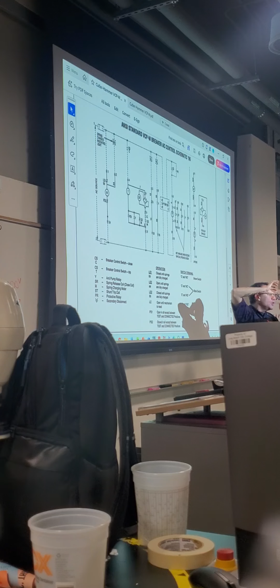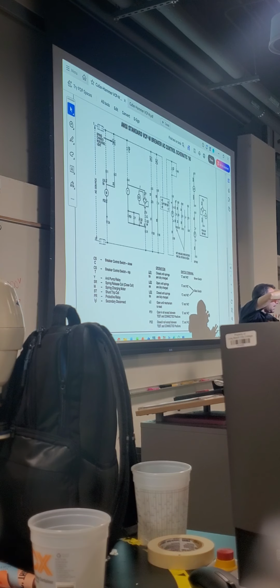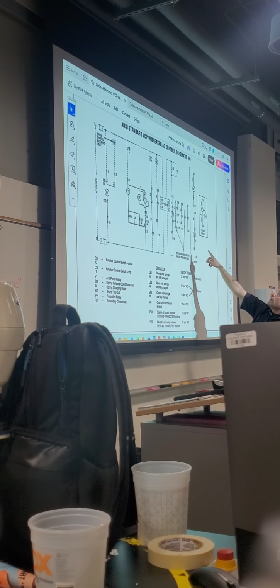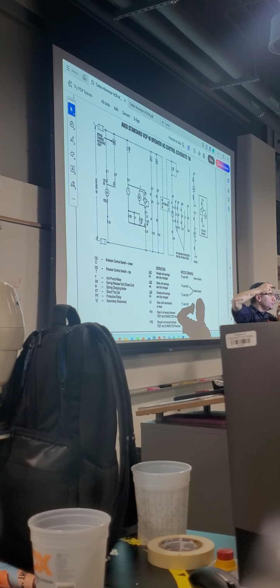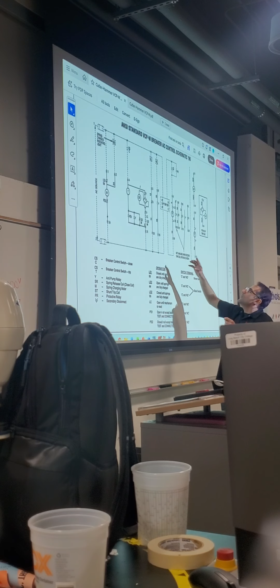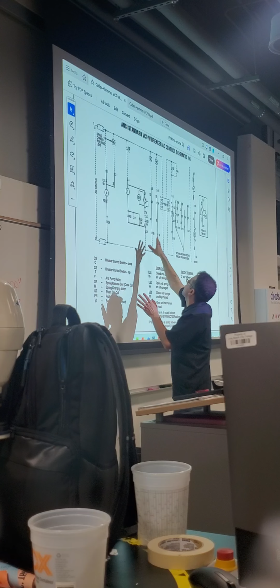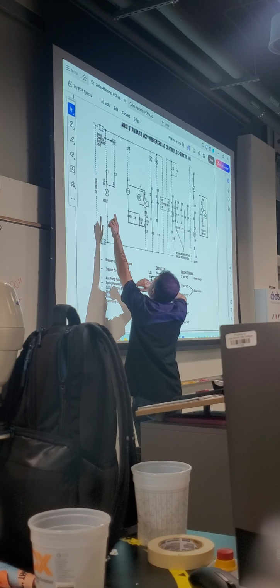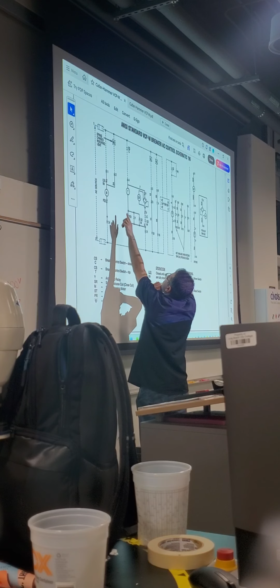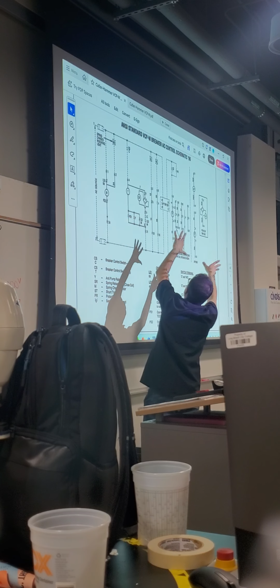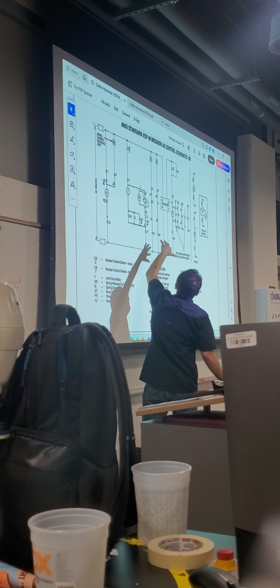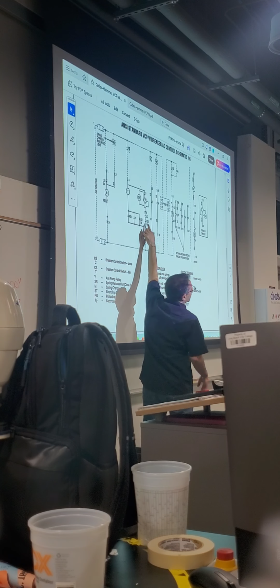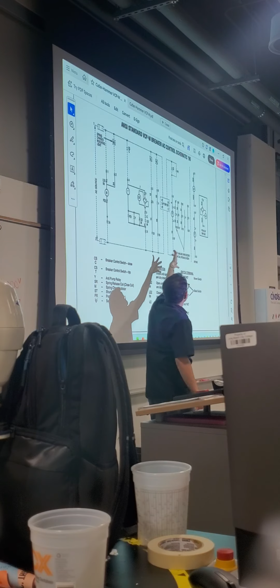We just need to understand which pins to apply the voltage. You have some coils. Coil is what you energize. You apply the voltage to the coil, and then it's gonna actuate one of these contacts. So by applying voltage to one of these coils, you're gonna change the status of one or multiple contacts. That's what it means.